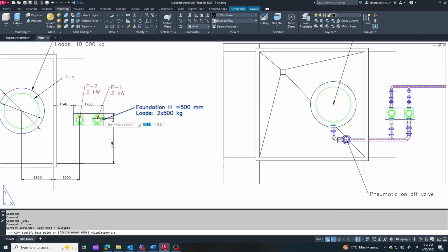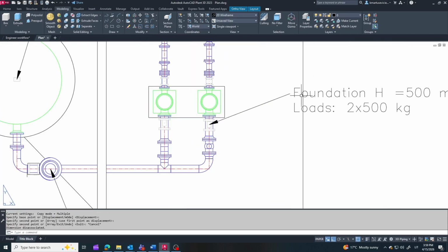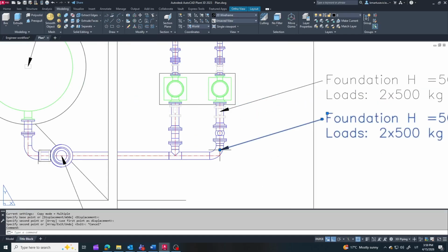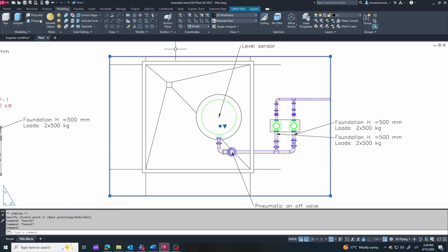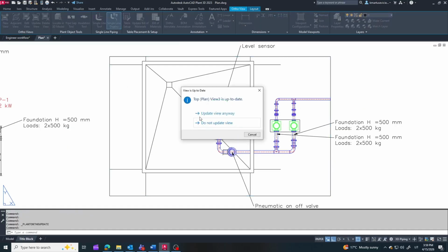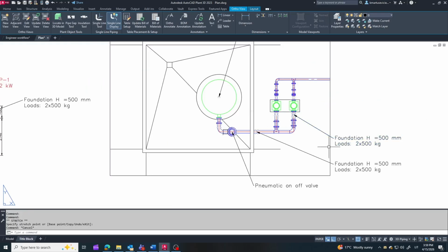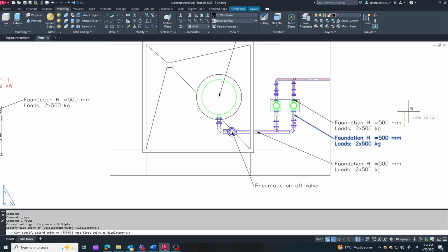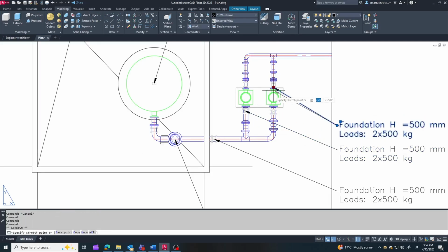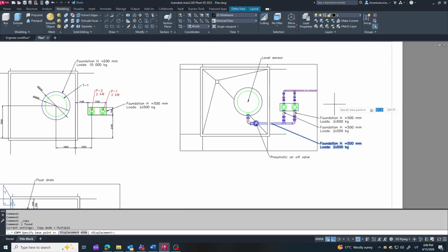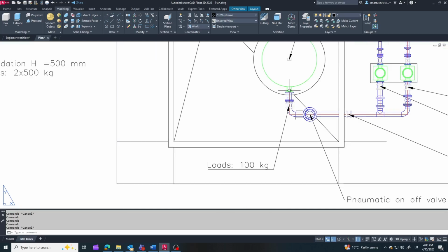Let's get back to the civil engineers and define where the pipe supports should be. For this task, we need to specify the support location, the load it must carry, the height from the ground, and also define the base plate needed for the support leg. How do we estimate the load on each support? A simple approach is to assume that each support takes half of the weight from the pipe section on both sides. When calculating the load, include everything that adds weight: pipe material, fluid inside the pipe, insulation, and heavy components like valves and instruments.